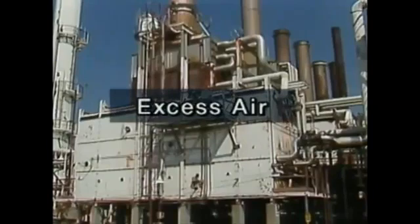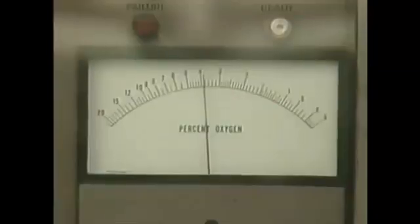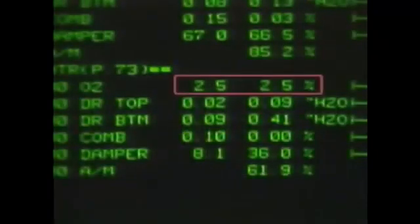Now, excess air readings are based on analysis of the flue gas. In general, this analysis determines the percentage of oxygen in the flue gas, and that percentage gives an indication of excess air. Furnaces normally have draft and excess air targets or acceptable ranges. Operating within the targets can save money in fuel costs.